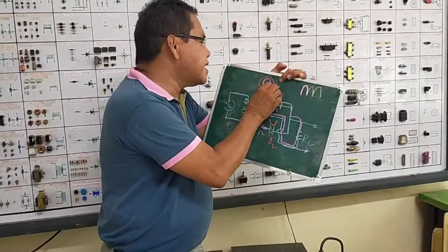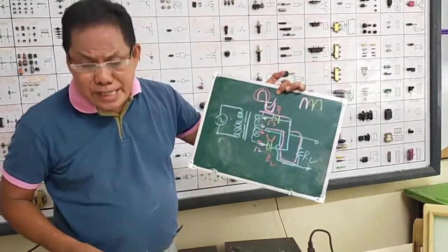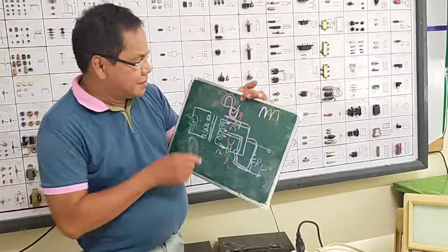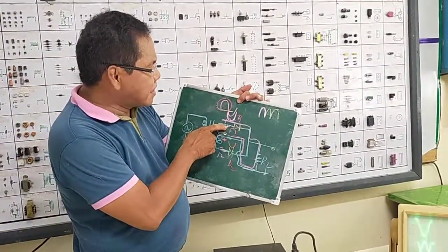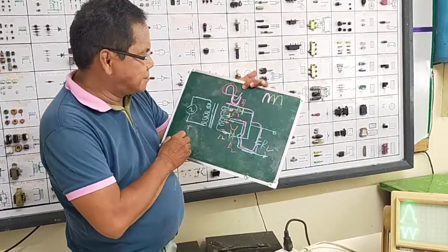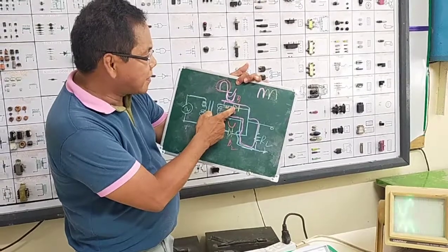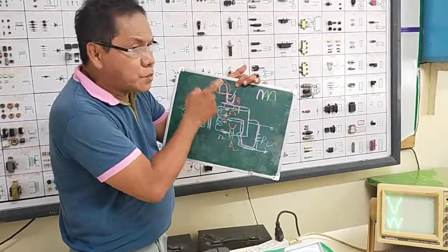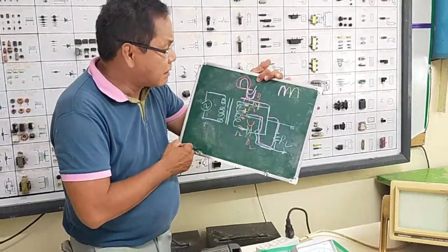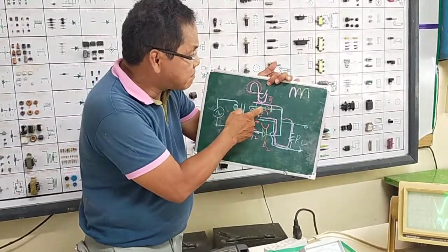But, in the next half cycle, which is negative going, the polarity changes. Positive becomes negative, and negative becomes positive. So, reverse bias already, in the negative half cycle, which is the next half cycle. This diode now is not conducting because it is reverse bias. Negative anode is positive.